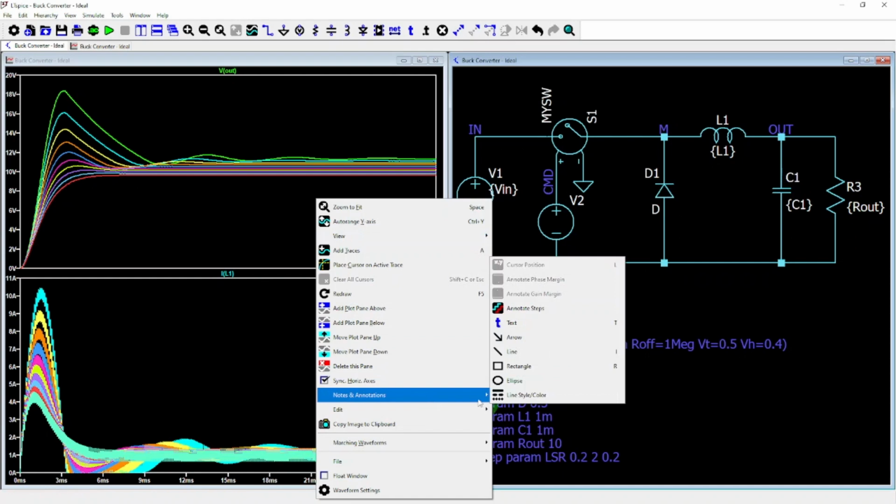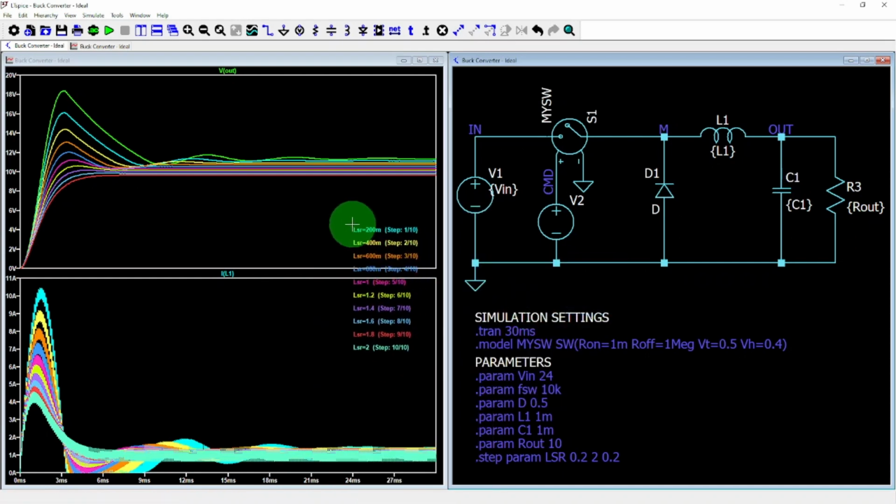However, the trade-off is a reduction in efficiency, since the damping resistor causes losses not only at startup, but also during steady-state operation. So now we understand what causes the oscillation at startup, and we also see that simply adding a resistor isn't a good long-term solution because it reduces efficiency. But why is that, and how do we evaluate efficiency?